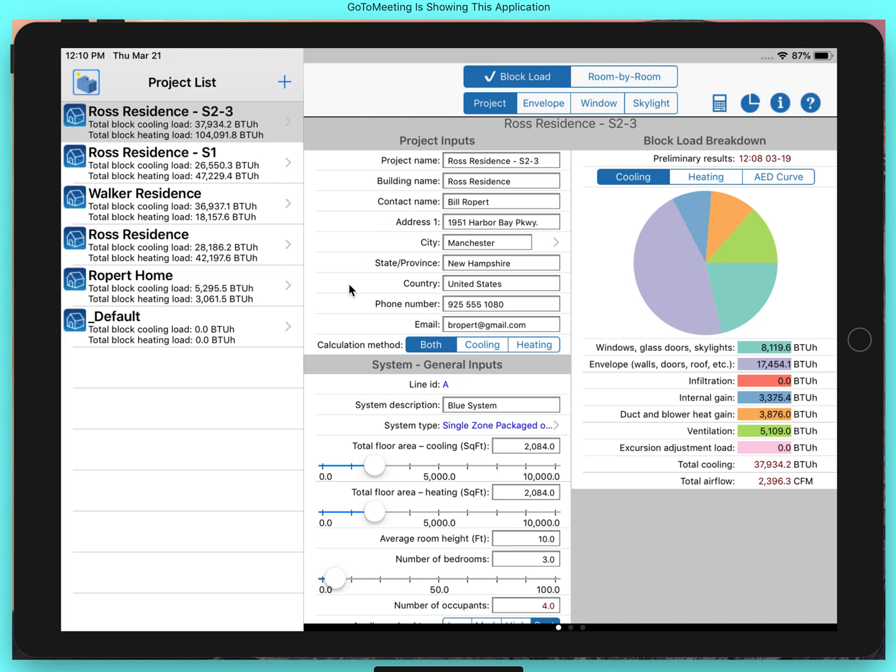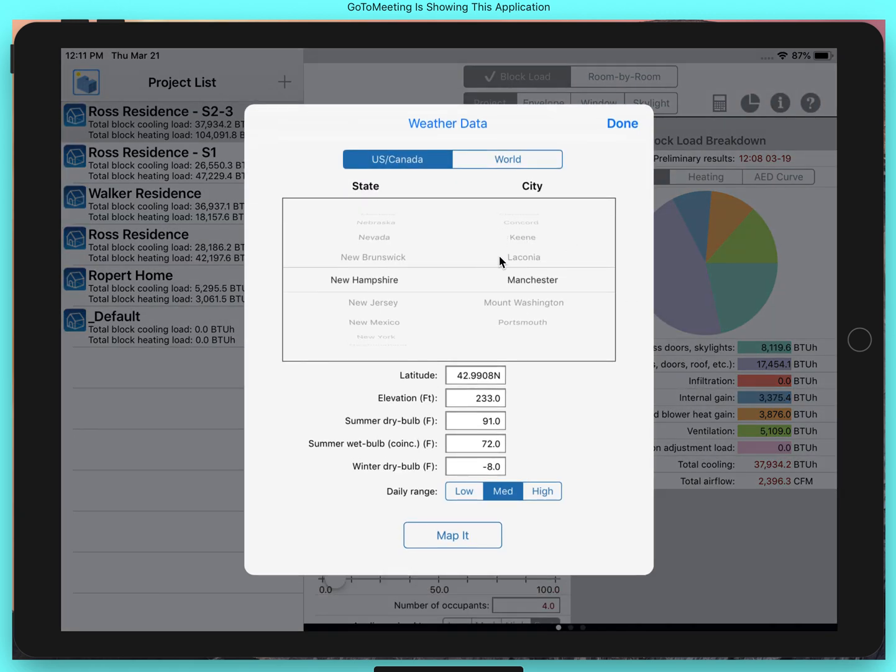All right, so this section allows you to enter all your demographic information, nothing too onerous here. The only thing that I do want to show you is the city input. So if you click this little caret there, it's going to pop up a form that allows you to select your city. And why you want to do that is you want to be able to get that weather data. Now your exact city may not be in this list, probably won't be because there's about 1,000 cities, but it's worldwide. So you'll want to select the city that is closest to where you're located or where your house is being modeled.